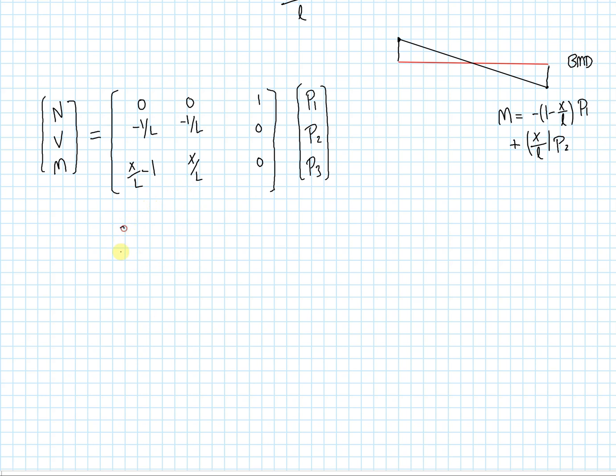At the same time, I'm going to have a slice flexibility matrix that has the following properties. 1 over elastic modulus times the area, 0, 0. It's going to be diagonal, so I will have zeros in the off-diagonal terms. 1 over the shear modulus, A prime. Here, A prime is referring to the area of beams that carry the shear force.